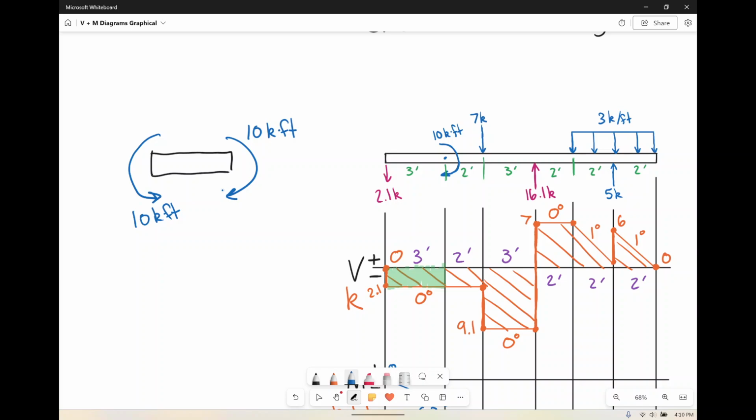Cool. So if I've got a beam, just imagine a ruler and take your hands and put your fingers in the direction of that moment. As you're coming around, you're going to push up on the center of this beam. What shape is that going to make this beam? Well, that means that this beam is going to pop upward like that. If you bend it that way, it's going to pop up. And that creates this shape, which if you put some eyeballs on this, that's a sad face.